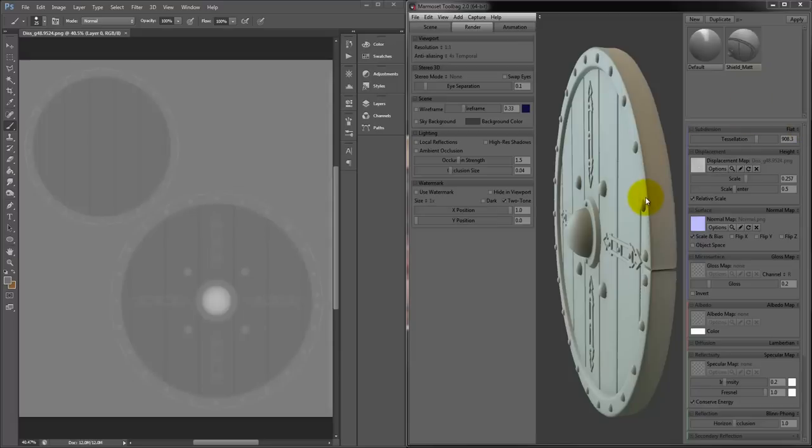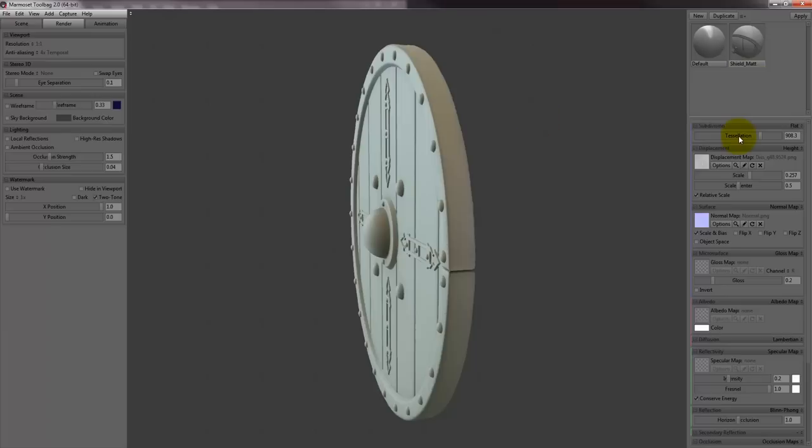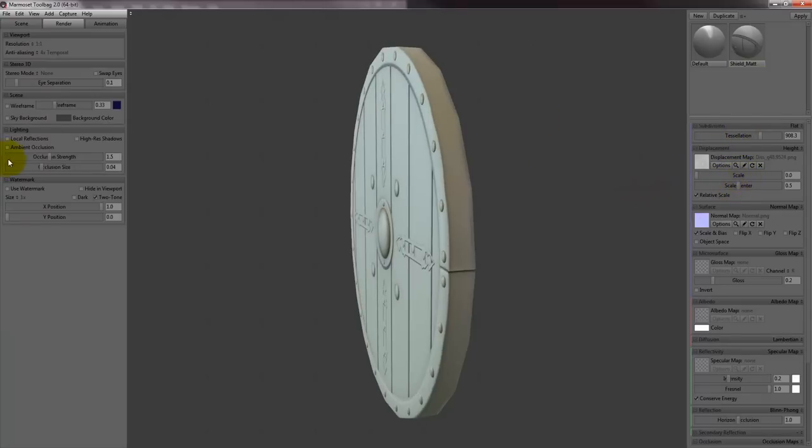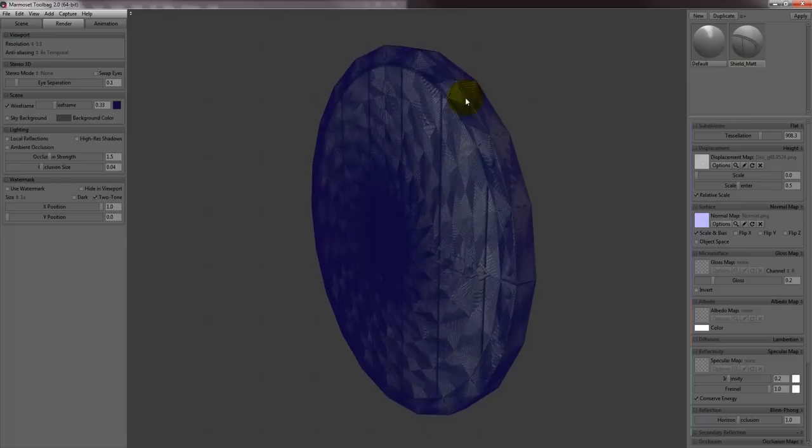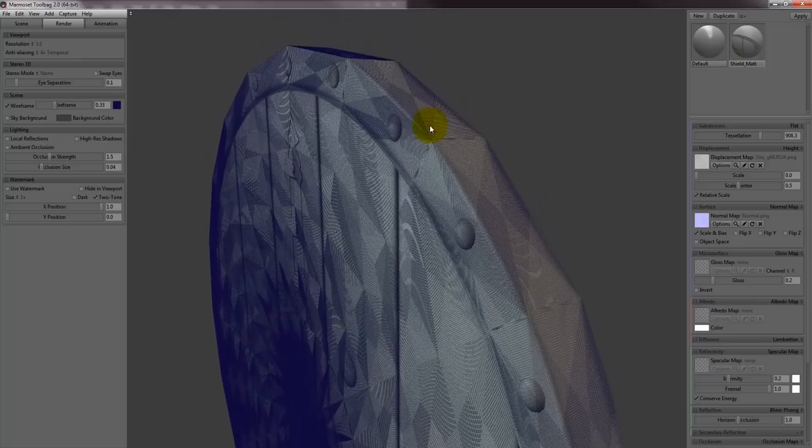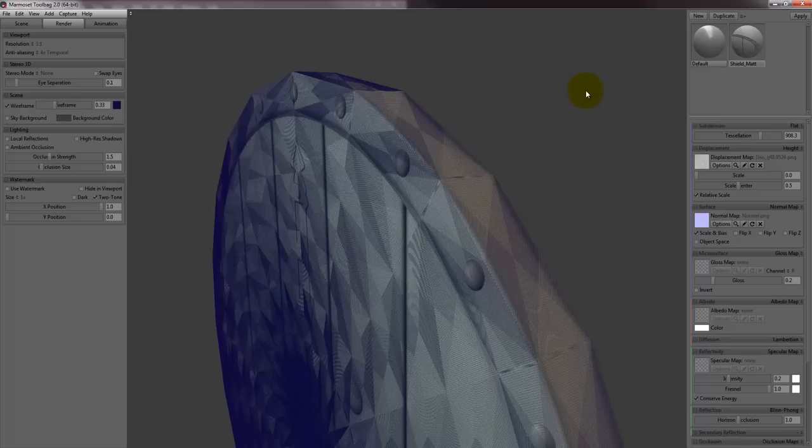Now, before we move on to generating height maps for yourselves, I want to revisit vertex normals, because whilst I've been demonstrating the displacement in this front area of the shield, all the vertex normals there are in the exact same direction. And I would like to show you the results of the displacement in an area that has less uniform vertex normals. So let's go back to full screen, take the displacement scale back down to 0, bring up the wireframe and zoom into this area here. So this time, as I increase the displacement scale, I want you to watch the vertices along these edges.